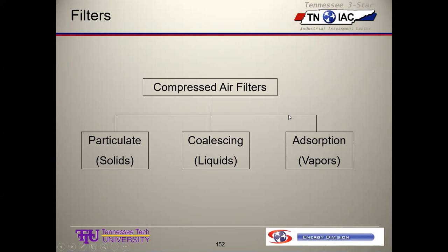Okay, a little bit on compressed air filters. There are filters for particulates and solids. There are coalescing filters for liquids and absorption type filters for vapors. So it depends what your system is used for and what's dangerous or potentially damaging. I mean, all systems have particulate filters, but the quality and the level and all that sort of thing depends on how sensitive you are to some of this stuff and whether or not you're trying to filter vapors. It just depends.